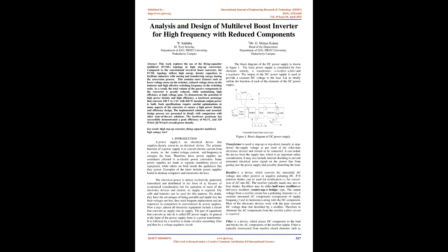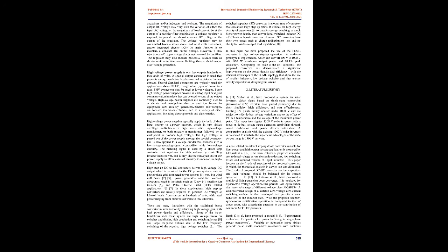Transformer is used to step up or step down, usually to step down, the supply voltage as per need of the solid-state electronic devices and circuits to be connected. It can isolate the device from the supply line, which is an important safety consideration. It may also include internal shielding to prevent unwanted electrical noise signal on the power line from getting into the power supply and possibly disturbing the load.